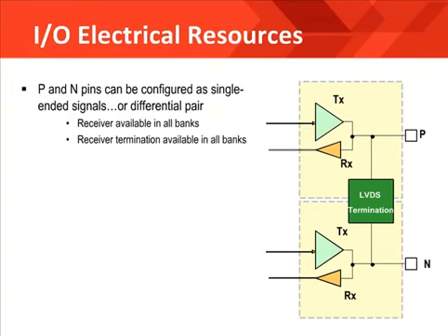This slide is just trying to show you how differential pins work in Xilinx FPGAs. Each pin in the device can be configured as single-ended or differential. But note that if the pins are going to be used as differential, you have a pre-assigned pair for each pin associated with the package. Note that these limitations have an impact on your pin layout, so if you're planning on using differential I/O standards, make sure that you lock your pins appropriately. And be sure, when planning to lay out your design, to use the PlanAhead software.